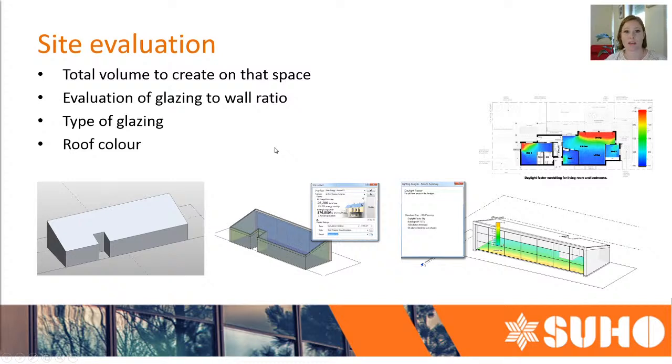When we start cutting into that space, especially in this example, then we might look at daylighting as well. So the diagram on the right is actually an example of daylighting. It was done as part of the BDAV, or Design Matters 10-Star Challenge, and this used to be what our 10-star home looked like. There were some other reiterations of it as well, but being on the south, we wanted to make sure in this instance that bedroom 2 had enough lighting.